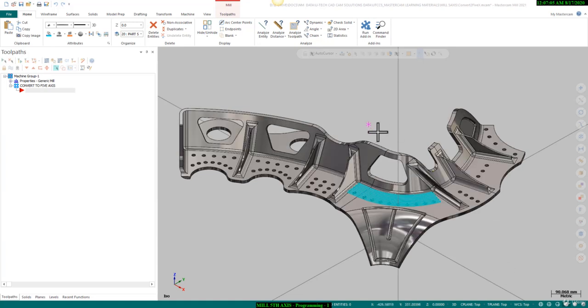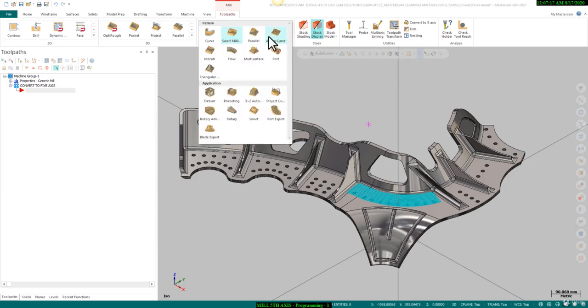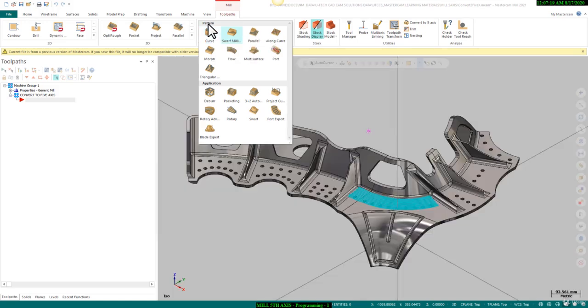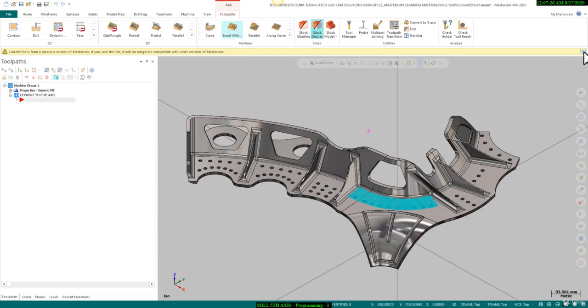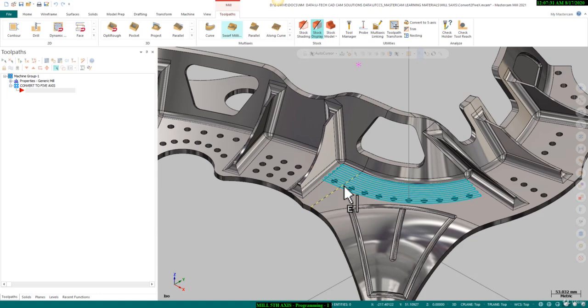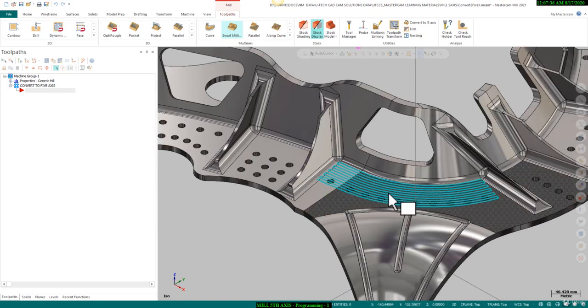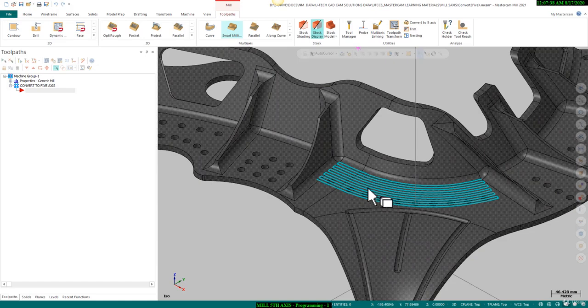So in this session I will teach you some 5th axis toolpaths. Let's start. We will go to the toolpath tab. Here you will get multi-axis toolpath options. In this strategy you will get many options, like pattern finishing, and some applications for profile finishing. First of all, I will show you how we can convert a 2D toolpath into a 5th axis toolpath. I will create a 2D toolpath by following this curve, and then we will convert that 2D toolpath into a 5th axis toolpath.